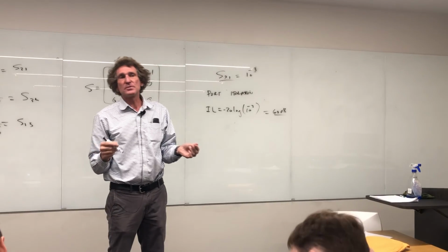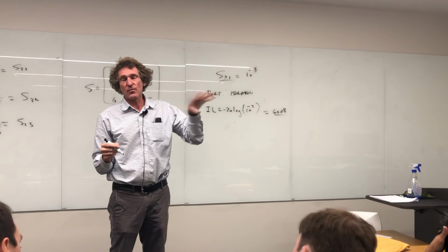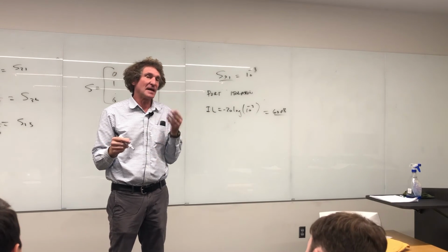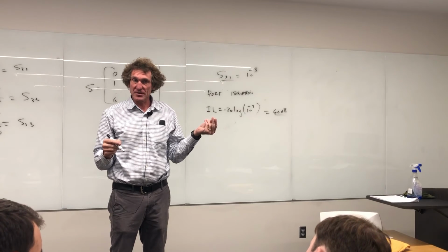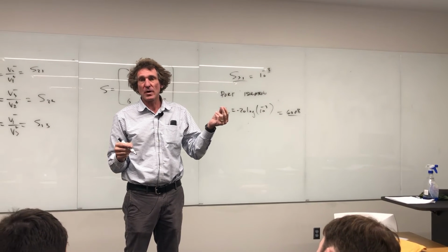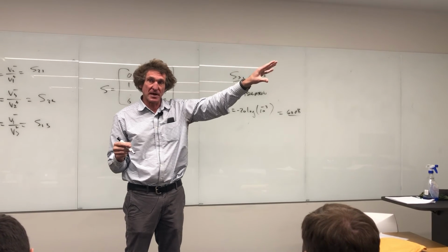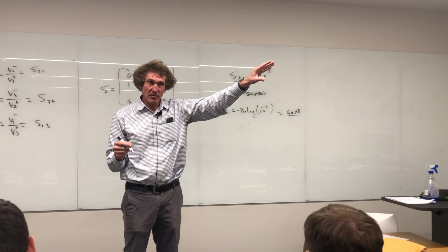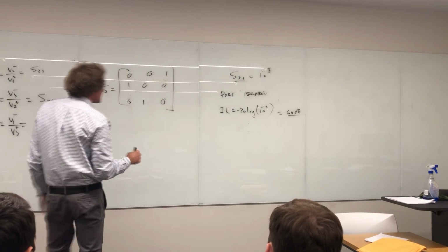All the other problems in his book regarding that, in the examples, he'll say for a 4-port, you're going to get something called isolation loss. Then there's going to be the insertion loss, the S21. But always when I ask this question, it will be relevant to the port it enters and the port it comes out. Follow me, class? That will be it.